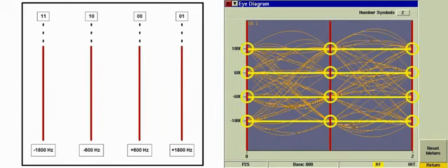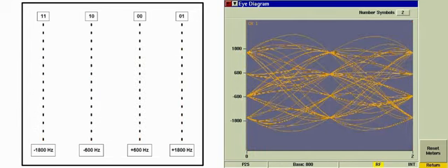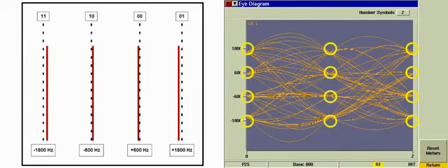With a good P25 signal, the line should cross precisely through the point at which the vertical and horizontal lines meet. A signal with low symbol deviation will have imprecise crossing points.